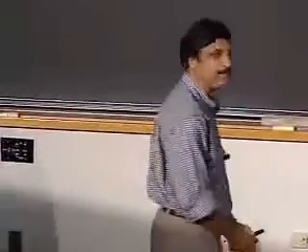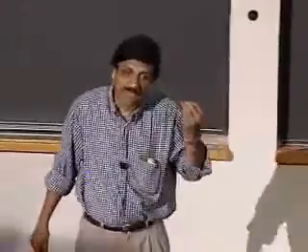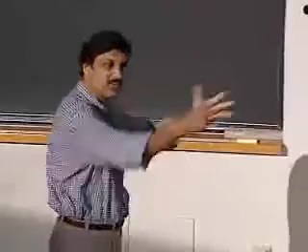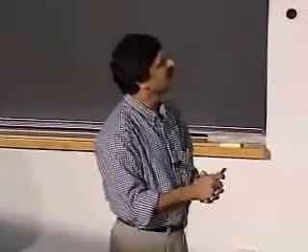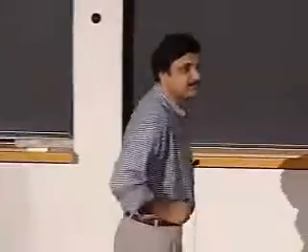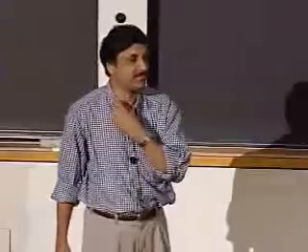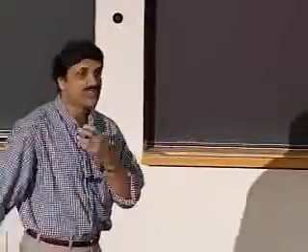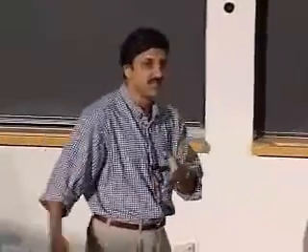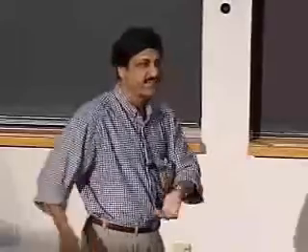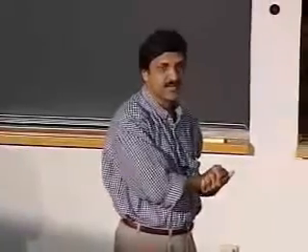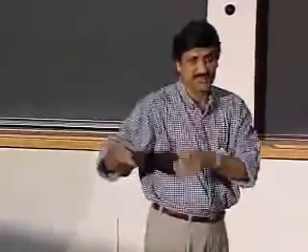Well, why steady state now? Hopefully I've convinced you that looking at the response of circuits to sinusoidal drive is important and interesting, because you can go long ways from there. What about steady state? Well, when you listen to music, so you have an amplifier, what you're observing, by and large, is the steady state behavior of the amplifier. You're listening to something over many seconds or many hours. And for most of our common circuits, the transients die out very quickly. And the transients are quite complicated, and they die out quickly.